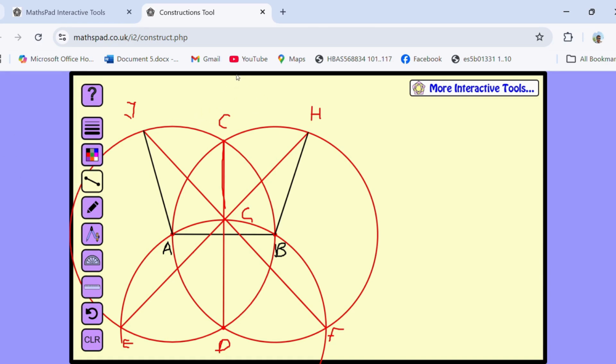Now we don't have sufficient space here, but you can draw the other two sides, taking AI or BH as a radius and I and H as centers. You should construct two arcs, and you should join the intersection of the arcs with I and H. Then you will get the remaining two sides. In this way, you can draw a regular pentagon when side is given.